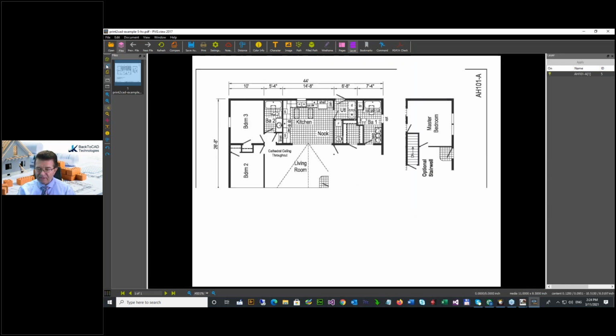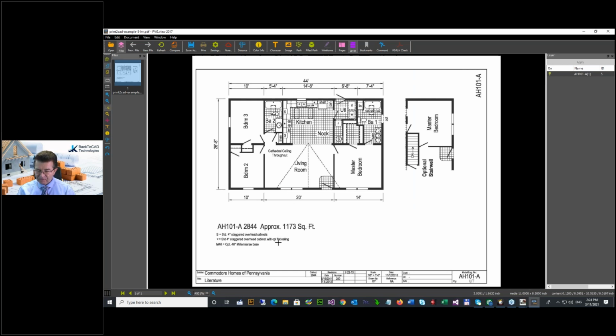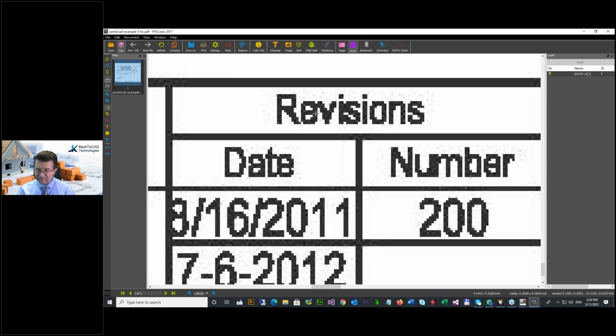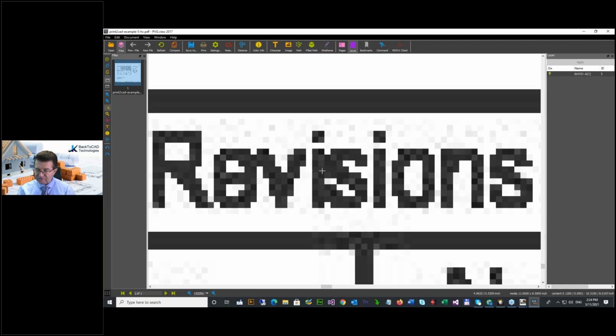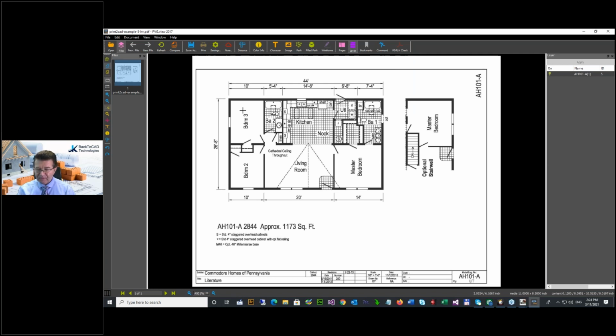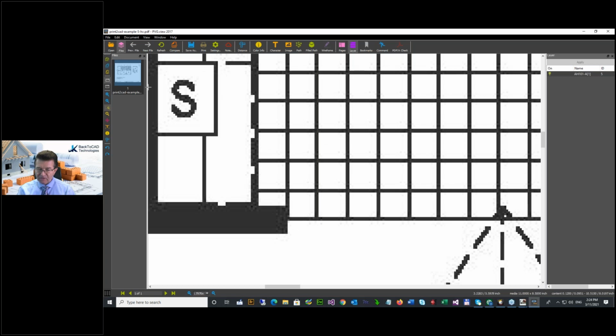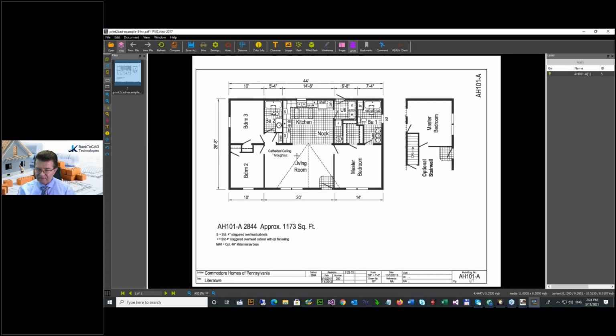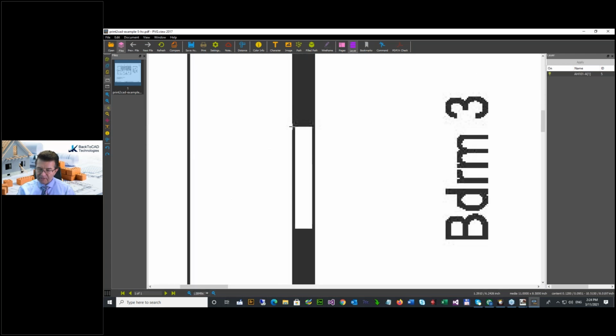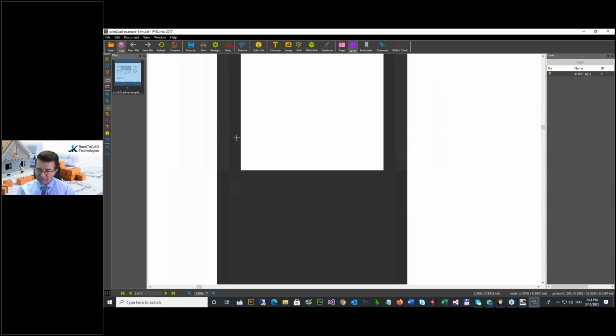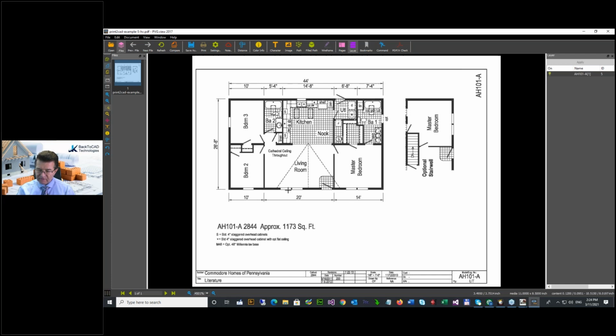And here you really need an artificial intelligence method if you want to recognize these revisions as revisions. You can see I will connect it with S. This is what we have to do every time if you have a terrible quality drawing, and I show you what you can activate in this kind of drawing. Okay, and look, for example, the walls. This is maybe what you want to recognize as an outline, and here you need a window. It's a center line tracing. Wall recognition is very important.